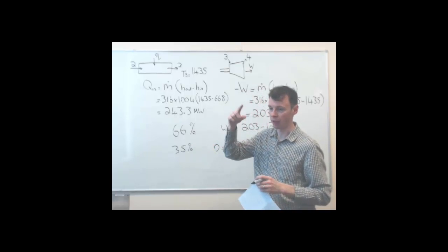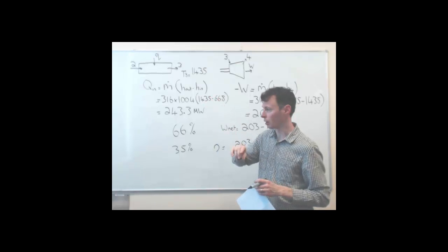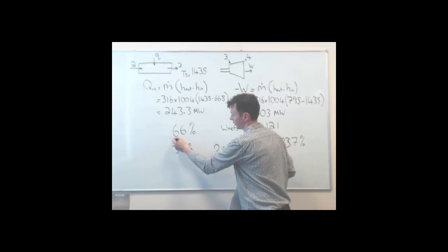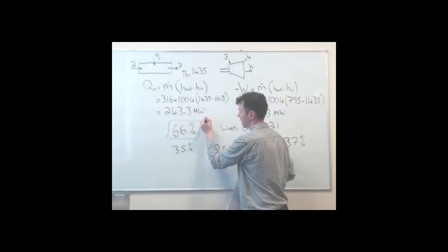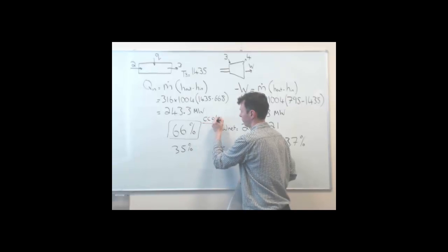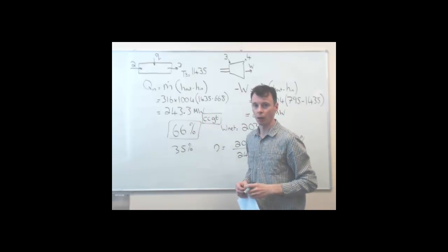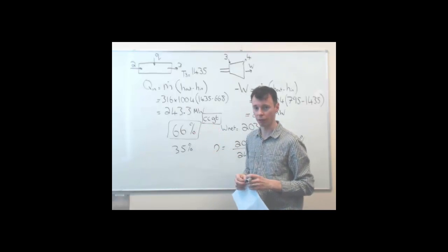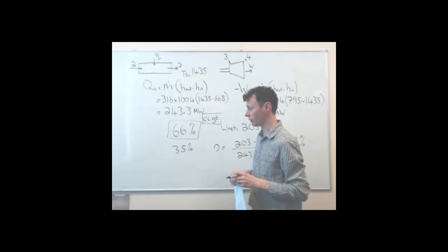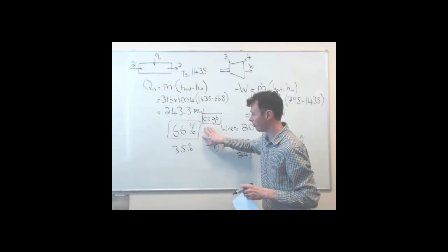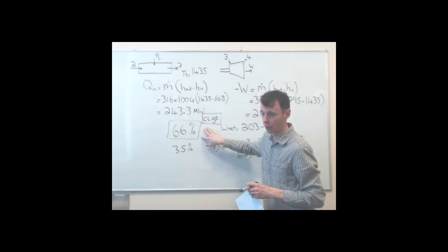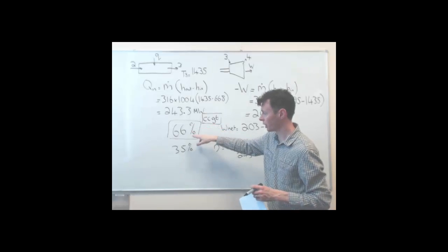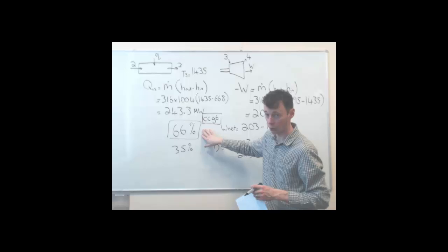You might pass the steam through and reheat it and things like that, but you still just have effectively a pseudo single cycle. So that's why combined cycle gas turbines, or CCGT, as their acronym goes, are very, very efficient. Gas is a fairly clean burning fuel. It has half the carbon intensity of coal. So that's why when the coal price went up in the 1980s, a lot of governments, especially in the UK, switched from coal straight to gas because your station efficiency is almost twice as much.